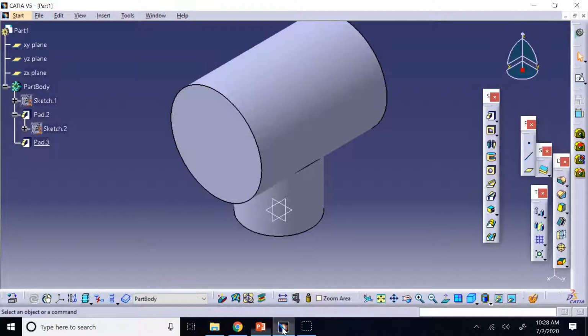Now, there is the exact opposite of extrusion, which is this guy, cut extrude. Here we call it pocket. So this one, instead of creating a prism, it will hollow out a prism. So let's say here, for example, now that I have these extra flat surfaces, not only can I choose my original planes, I can also choose any of the new surfaces that are flat, and I can draw a sketch on these now.